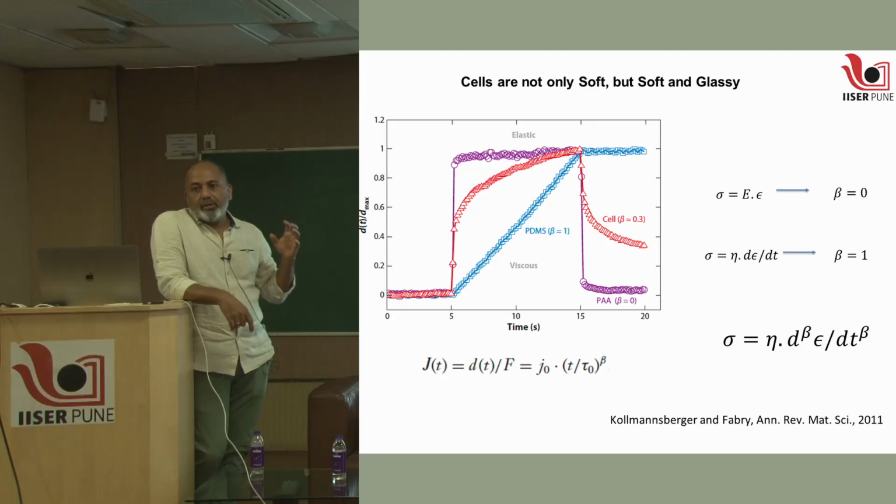And we always know that stress and strain are proportional to each other, and the proportionality is the modulus of elasticity, or Young's modulus as we call it. Many times, even in the previous talk, we report the Young's modulus of a material to characterize whether it is soft or stiff. High Young's modulus means very small elongation of the wire for a given force or stress. So if the material is stiff, the Young's modulus is high. If the material is soft, then Young's modulus is low.